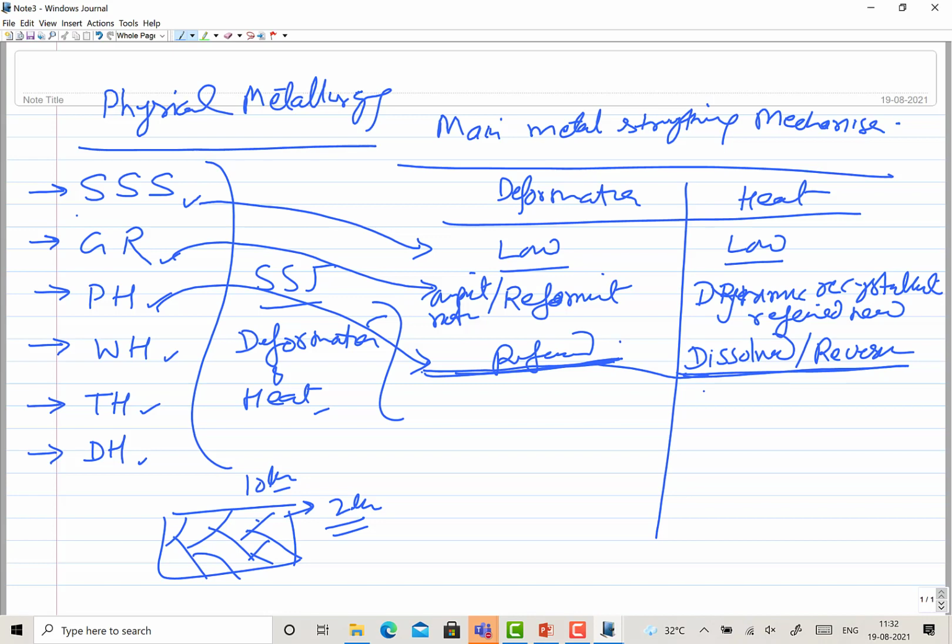So here in precipitation hardening you got refinement, but lost the precipitates, which got dissolved due to the application of heat or rise in temperature. So you may get lower strength as a combined effect. Okay, so your joint efficiency can be drastically reduced, say maybe 50%, 60% as compared to the base metal, because of these losses of the precipitates.